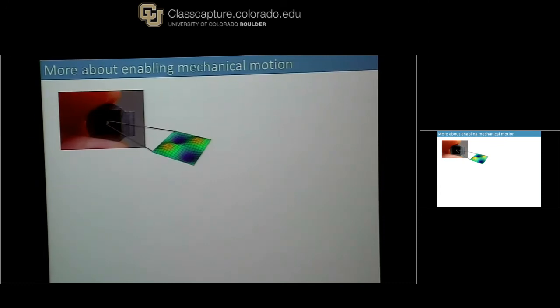And then we talked a bit about these mechanical elements that we use. They're the silicon nitride drums. I put a new picture up here to show you the scale of it. You can hold it in your hand and you can see the light reflecting off of it, and you can see this thin film that we're using. But it's very, very thin. As we talked about last time, it's 0.5 millimeter on a side and about 50 nanometers thick.